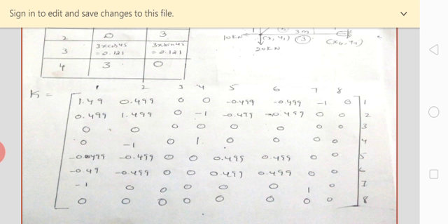Whereas for the second element, again it starts with 1 2 5 6, because you have taken the initial node as common for all the elements. For all three elements, the initial node is 1. It always starts with 1 2. For the elemental stiffness matrix of the first element, it starts with 1 2 3 4. Similarly for the second element, 1 2 5 6. Similarly for the third element, it starts with 1 2 7 8.